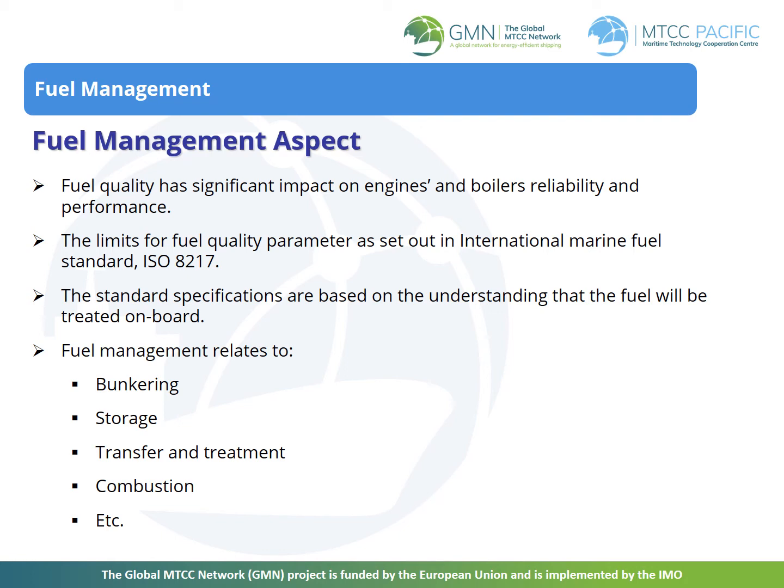It is well known that higher density fuels and higher water and sulfur contents all reduce calorific values, which represent the energy content of fuel. Additionally, higher sulfur contributes to undesirable air emissions of sulfur oxide, and high metallic impurities put the engines and boilers at risk.